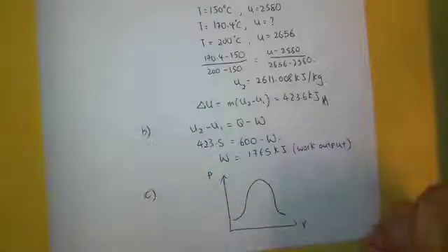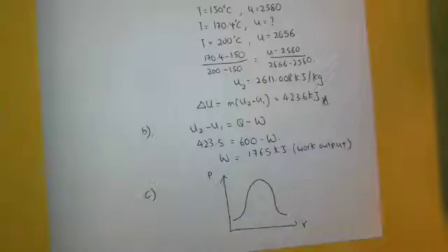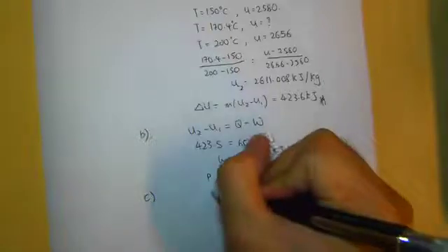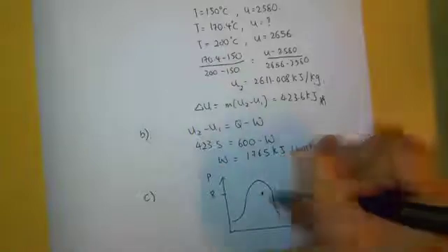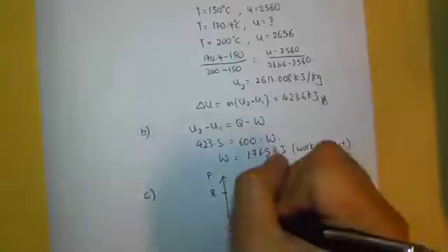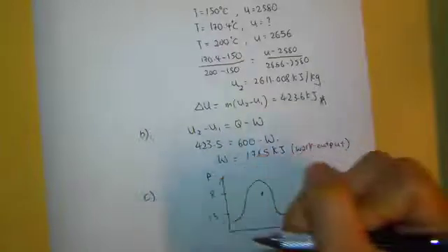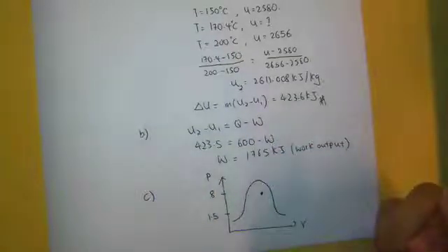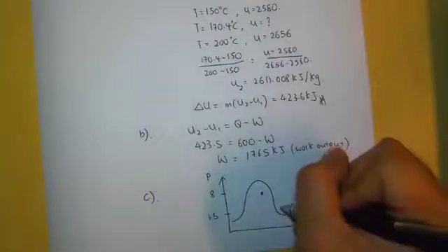Okay, so first of all, you can draw your bell curve first. So the initial stage is wet steam at 8 bar, so 8 bar, wet steam around here. Okay, the final state is 1.5 bar, and for the final state of 1.5 bar, it is in the superheated region, so it must be here.